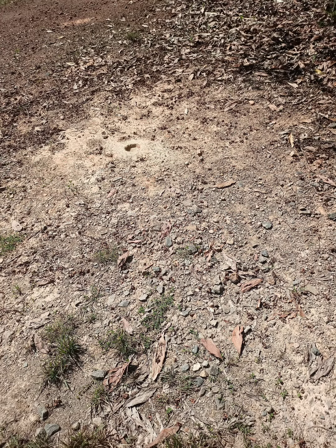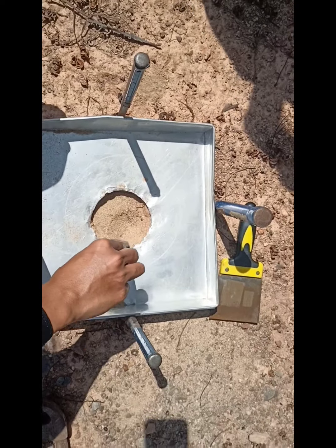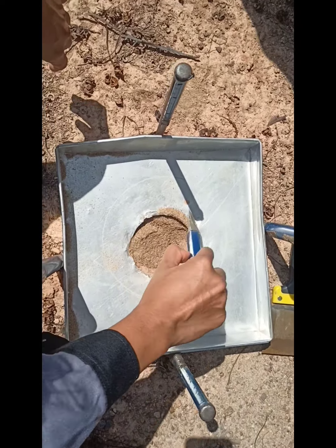The procedure to conduct this experiment is, firstly, the site is cleaned and leveled using a scraper for an area of about 450 mm square, and the metal tray with central hole is placed on the prepared surface. Also, using the central hole as a pattern, excavate the soil using a trowel up to the required depth, and the loose soil is carefully collected into the container and weighed. So the sand pouring cylinder is refilled with sand such that its weight is regained.